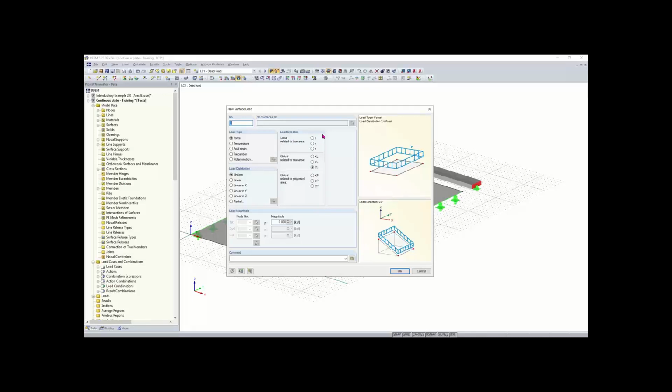Just a quick something to point out, the local axes, if you ever see lowercase coordinates, those relate to the local axes, and the global axes are the capitalized coordinates here. So we'll keep that as the global z coordinate. And now we just want to add a magnitude to our load. So this will be a magnitude of 0.21 for our KSF. And now we can click OK.